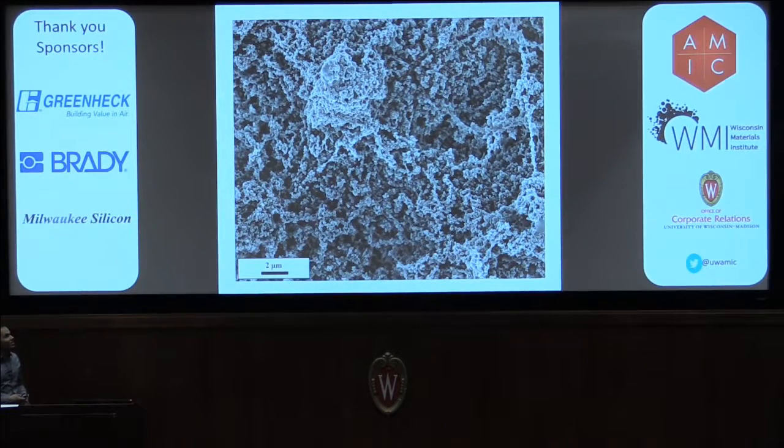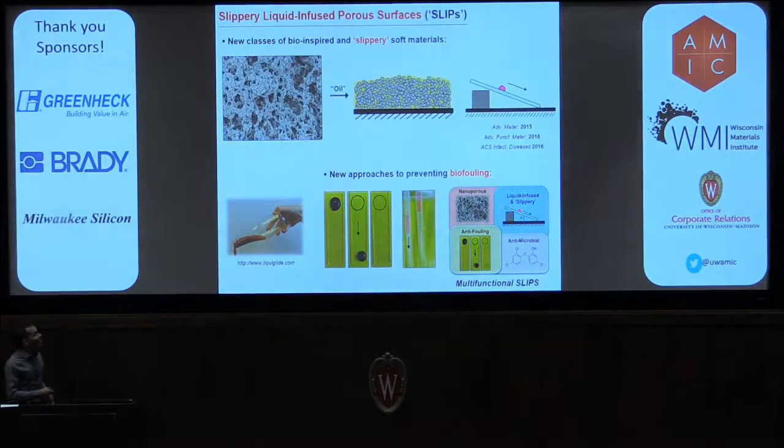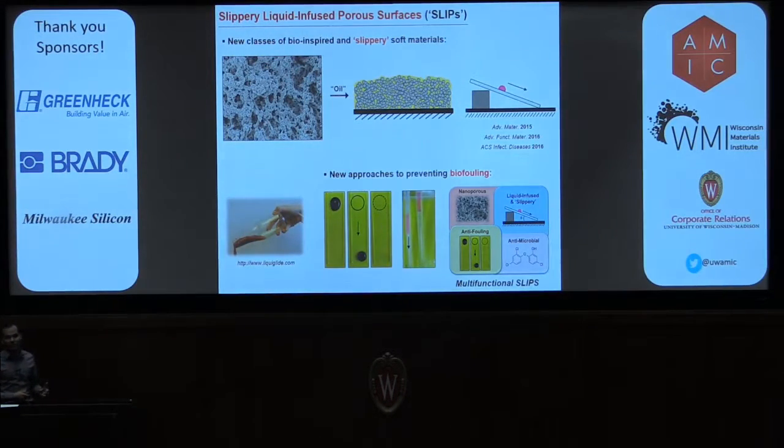And that's exactly what has been demonstrated with slippery liquid-infused porous surfaces, or SLIPS, a technology that was developed at Harvard by Professor Joanna Aizenberg. The basic principle is that if we start with our material, a hydrophilic polymer matrix, and we infuse an oil phase into that polymer, we can create a defect-free surface. The oils that we can use can range from perfluorinated oils to silicone oil or any other type of oil, such as olive oil or coconut oil, for example.